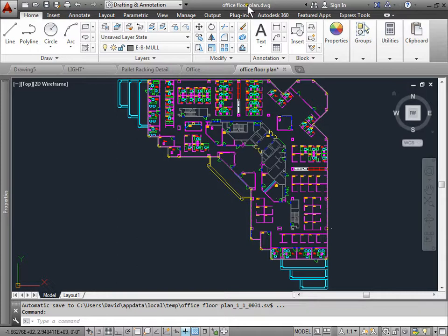Try to use some common prefixes so the name of the layers can be related to the drawing components to make it easier to manipulate the groups of the layers. If you stay consistent with the way that you name your layers, you can save a lot of time by creating and saving a drawing as a drawing template or a .dwt file with layers, line types, and colors already assigned.